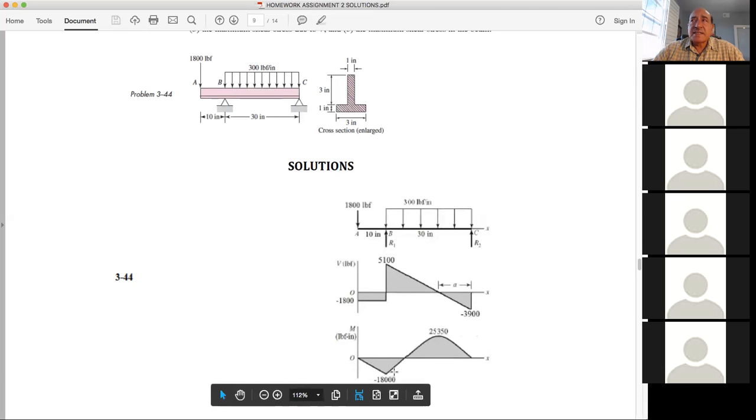They're giving us axial. So we can also combine them using Mohr Circle that I talked about, so that we can find the maximum principal stresses and determine if they exceed any allowable. So this is the kind of idea behind the assignment here.